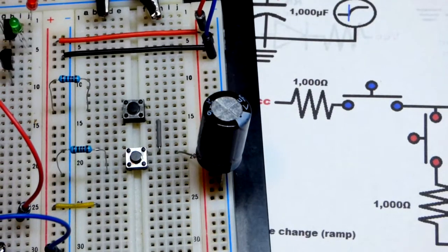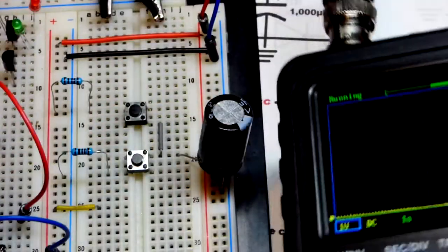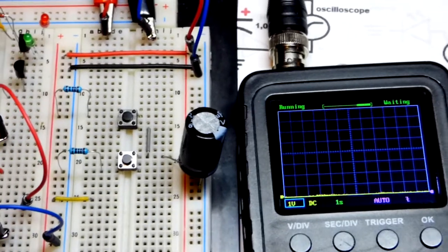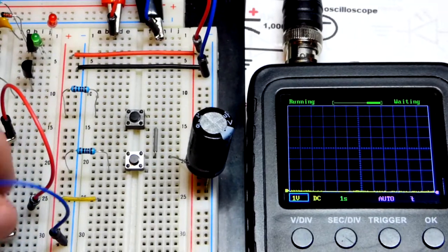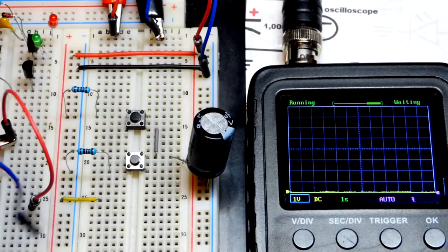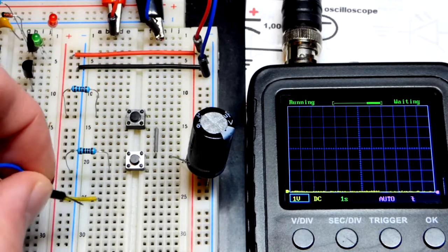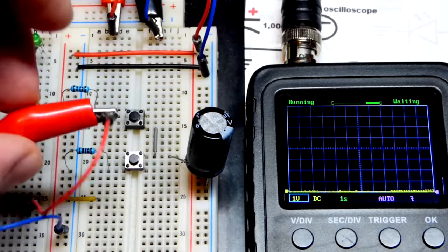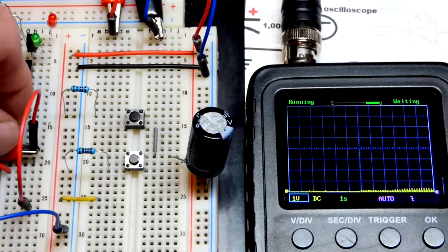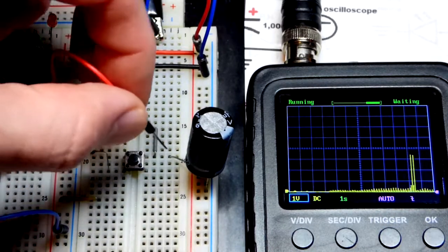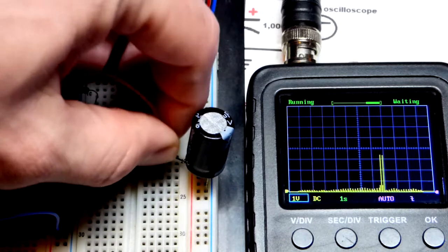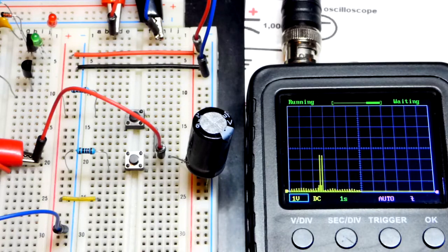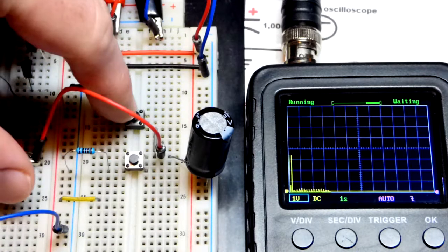So now we are going to grab the oscilloscope here and look at the waveform that we get, which of course is the RC time constant. So the black alligator clip, I just clipped it to a wire here. I'm going to put this wire to the negative rail, and we got the red alligator clip there. That's coming from the oscilloscope. We're going to put it to the capacitor so we can monitor the voltage of the capacitor. And there you can see it leveled off because we don't have all this noise anymore. Now it's actually looking at the capacitor voltage.